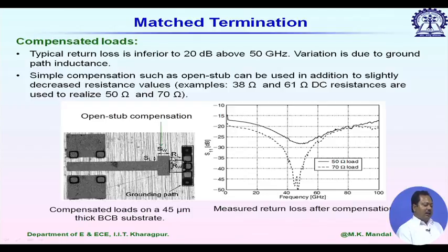In this picture, RW and RL show the width and length of that nickel chromium section, we call it a thin film resistor, and on the right hand side you can see one long black line, and on that we have 3 vias. Instead of 1 via, they are using 3 vias to reduce the inductive effect.